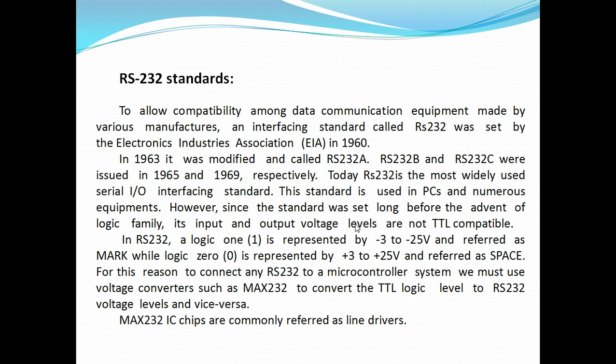Today's RS-232 is the most widely used serial interface standard for data transfer between communication equipment, or generally we can say between personal computers and microcontrollers. Because these RS-232 standards were invented before the microcontrollers, their voltage levels were different compared to TTL microcontroller devices. The TTL logic family uses logic 0 as 0 volt and logic 1 as 5 volt.